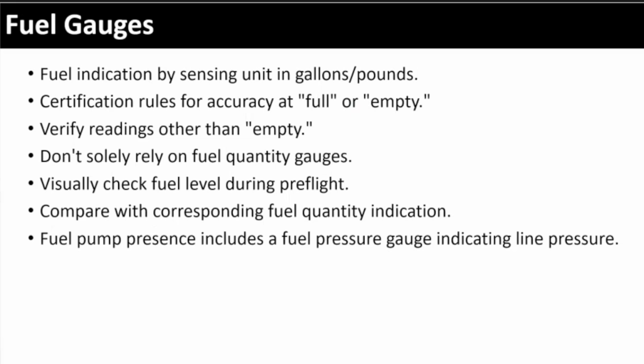So it's really important that when you're doing your pre-flight, you're not only looking at those gauges to see, hey, it's telling me I've got 3/4 of a tank on the left and I've got a half a tank on the right, right? It's really important to verify during a pre-flight, looking at the tank, looking inside to validate what you're seeing inside the airplane. Okay, don't ever just randomly trust. Don't just trust the fuel gauges. Okay.